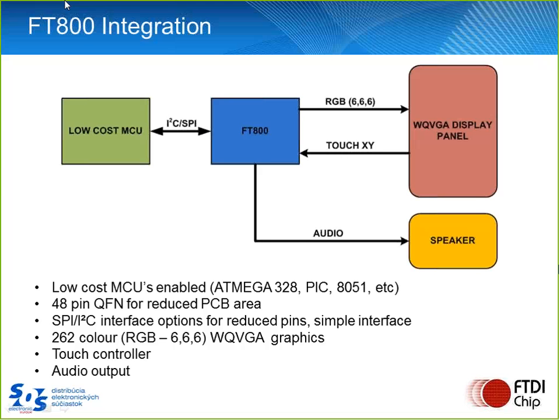What you're really looking at is that you don't need to spend the same amount of money because you have a lower-end MCU, a very standard basic display panel, and you don't need as much board space. Essentially, you can use any controller which your application is already running with, so long as it has an I2C or an SPI interface. This allows you to remain familiar with the controllers that you already have, and it allows you to be comfortable as you design in the